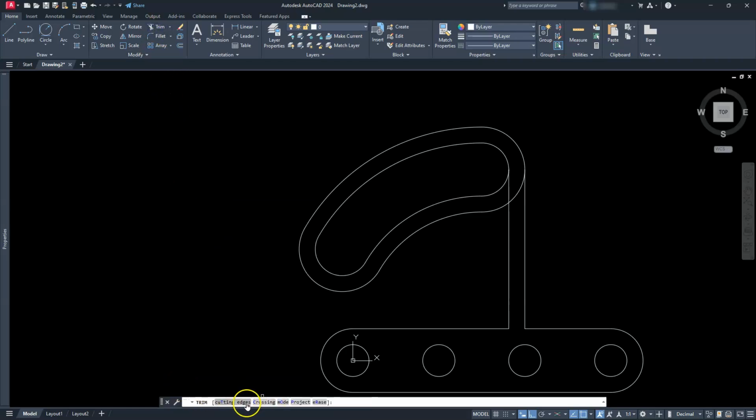Radius. It looks like I chose trim. Fillet. Radius. 20. And then I have more than one, so choose multiple, and go ahead and place them here and here. Likewise on the other side.